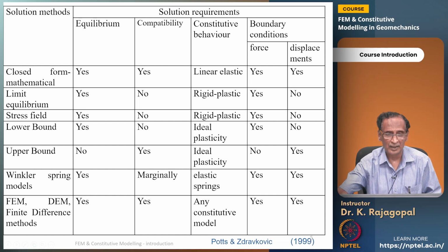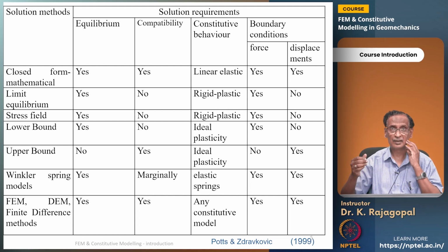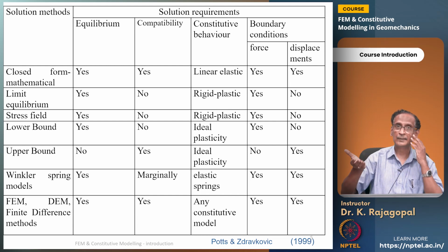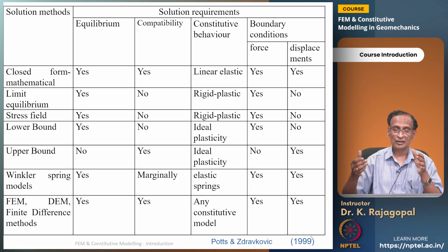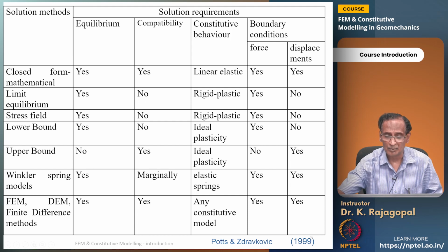Then the constitutive behavior, because all these mathematical models can only be applied for linear elastic problems. Like if you open any elasticity textbook, you will get a lot of solutions for the case of any loading on a surface, and we can get the deformations and then the stresses, and we can satisfy both the force and displacement boundary conditions by these closed form solutions.